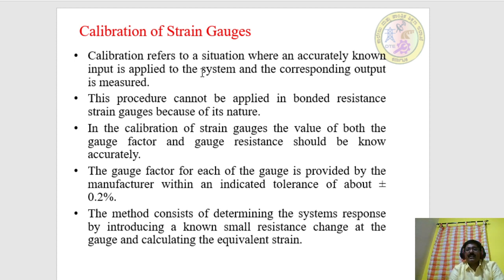See, the procedure cannot be applied to bonded resistance strain gauges because of their nature. Moreover, for calibration of strain gauges, the value of both the gauge factor and gauge resistance should be known accurately, otherwise it is impossible to calibrate.